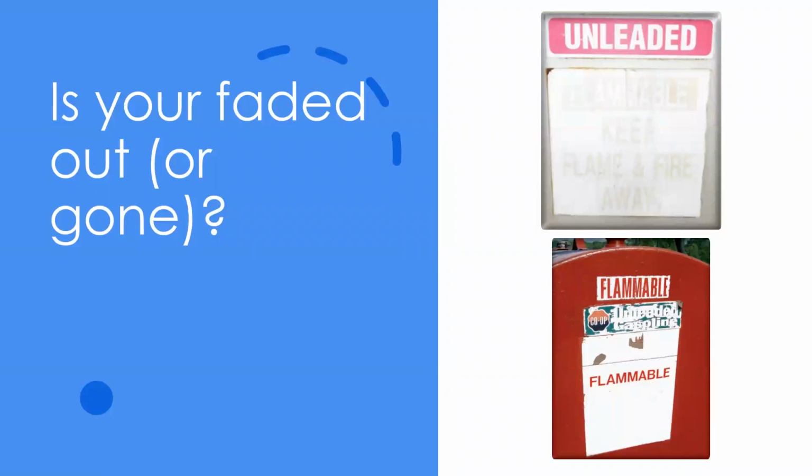All right, so first we're looking at the labeling here. We see this a lot. If your label is faded or gone or out of date, that's an issue. And here we've got our flammables, but any other kind of hazardous oil substance, including our flammables, would need a placard that shows the issues related to it. So if they're in transport, then you want to have DOT placards. If you are on site, your HAZCOM communication labels are important to have. So one of the two.